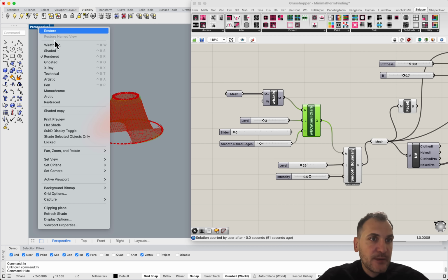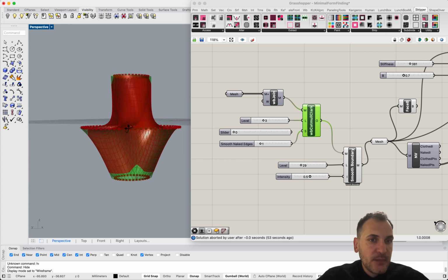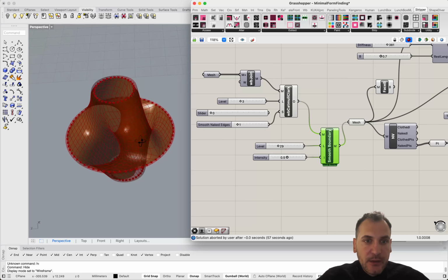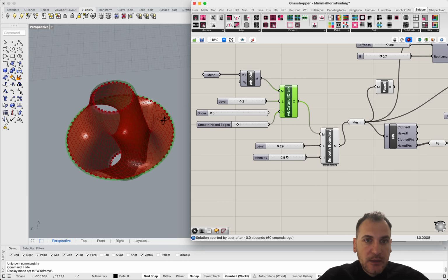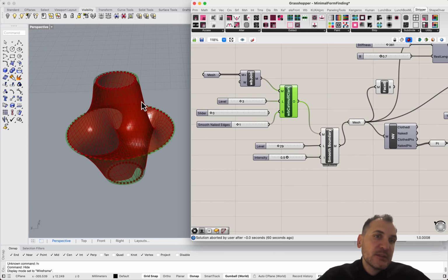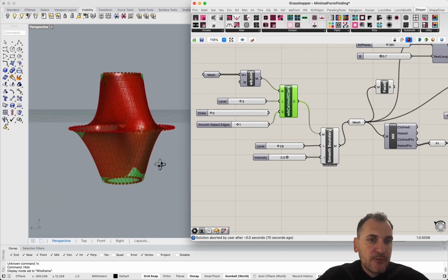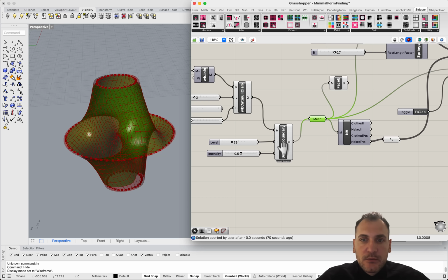So we will get a lot of faces, something like this. And when we smooth the boundary, initially you get, I mean, this will actually be kind of a circle, but we want, let's say, we want to work with other geometries. I'm going to show you why smoothing kind of helps. But you want to maintain kind of a ring that is uniformly distributed with vertices, right?